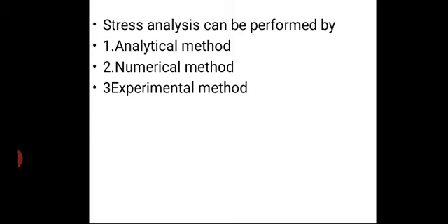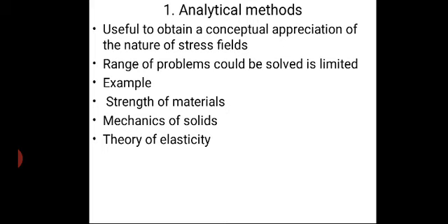So here there is the possibility of stress analysis, and this can be done in 3 different methods. One is the analytical method, the numerical method, and the experimental method. In analytical methods, we take from our regular mechanics of machines or strength of materials, or even from the theory of elasticity, where we are able to get a conceptual appreciation of the stress fields.